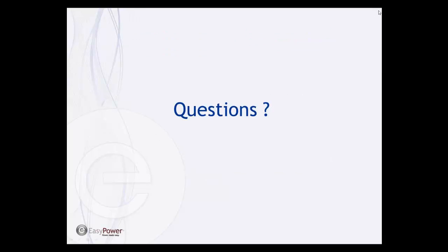So that will wrap up our discussion today. Just to wrap it up, we talked briefly about stability and arc flash instability and the way that the software goes through the simulation and how it evaluates the trip times and comes up with the incident energy. And we've also shown how that function from stability is used within the integrated method to come up with a bit of a simpler view of arc flash, but uses a lot of the same methods as far as the calculation goes. And then in the end, we showed a little bit of why you may use momentary versus integrated versus stability. So I hope you've enjoyed and you've learned something from this webinar.